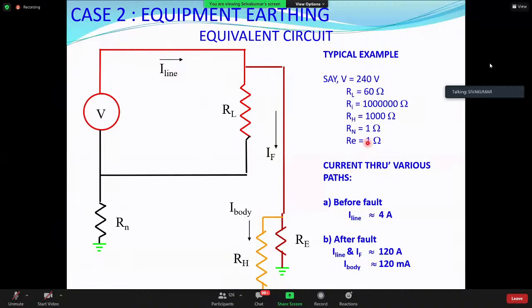So what you are doing is, even if no one is maintaining the earthing system, still the system should work. What they say is, equipment earthing with a protective earthing conductor. So you put a separate earth pit for the neutral, you put a separate earth pit for the equipment, and you interconnect the two with a solid conductor like a GI earth flat or copper earth flat run around the plant. You connect all the earth pits to the earth grid.